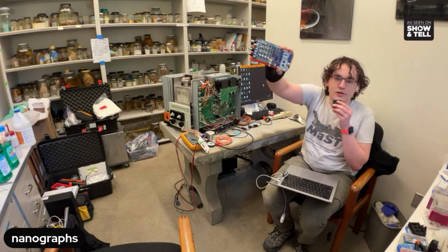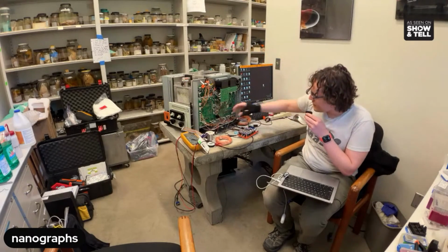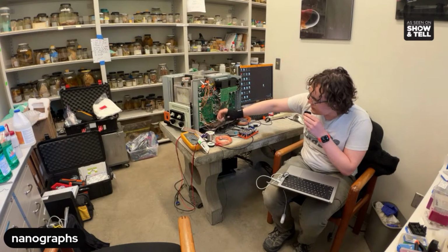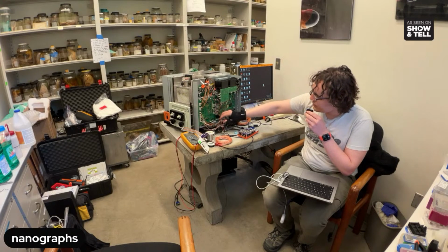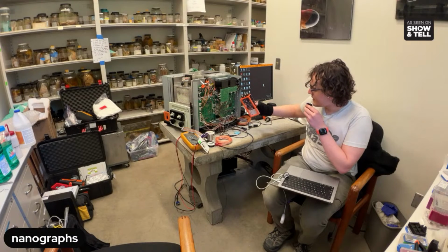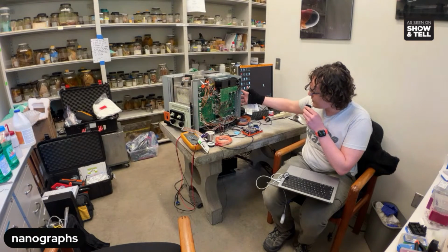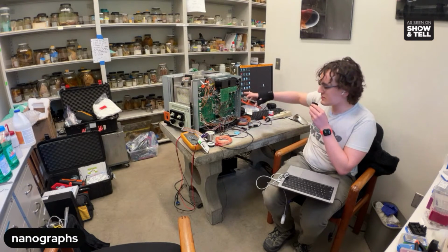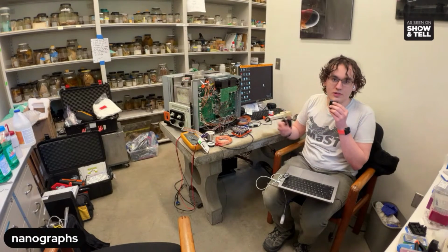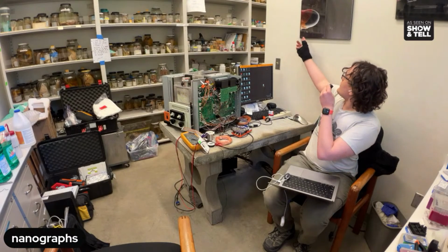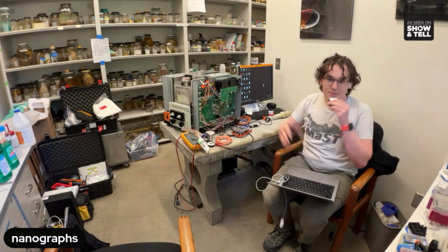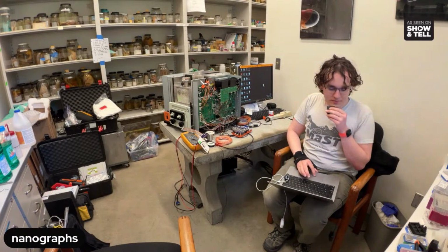So we are installing our open beam interface on it. We've cut some of the cables inside here that carry the scan signals, and we've attached some BNCs to that. We put a little relay in that lets us flip between the internal scan generator and the external scan generator. Then we're going to put all these connectors on this back panel right here so that we can just plug all our cables in. And then we'll just have our board on this, and they'll be able to take much higher resolution pictures with it. They already do some wall prints of some of their SEM micrographs, and we're going to be able to make bigger prints now because we can take higher resolution pictures.